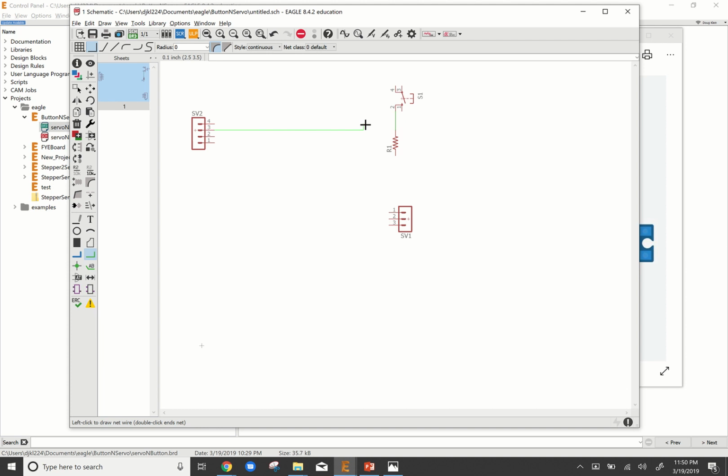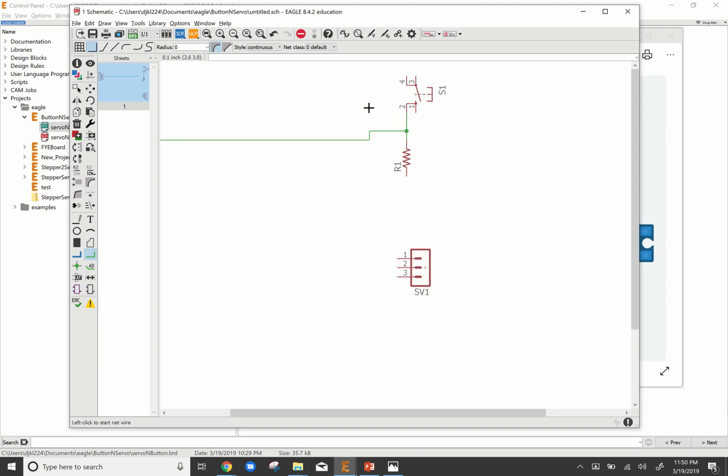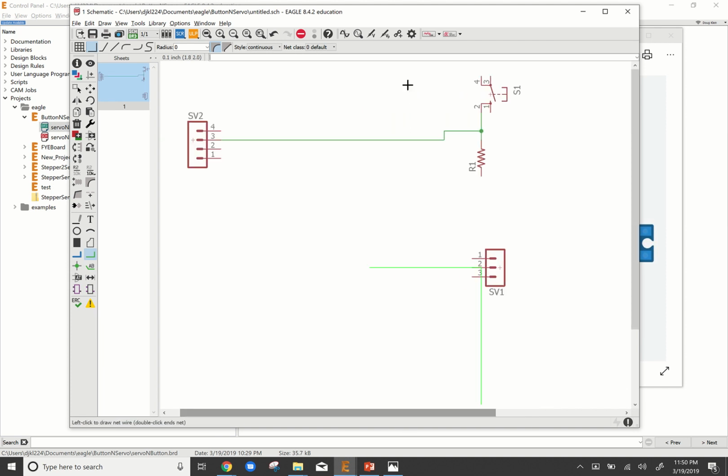I'm going to go into pin 3. All right. And then I'm going to come over from my power, come over from my ground, and you'll see I've met a couple of those constraints I've set, right? So I have my wire coming over, I have it reaching this, I have it going and getting my power and my ground, and I'm not seeing really any crossing of wires, which I think is a real positive. I'm going to add in my servo here.